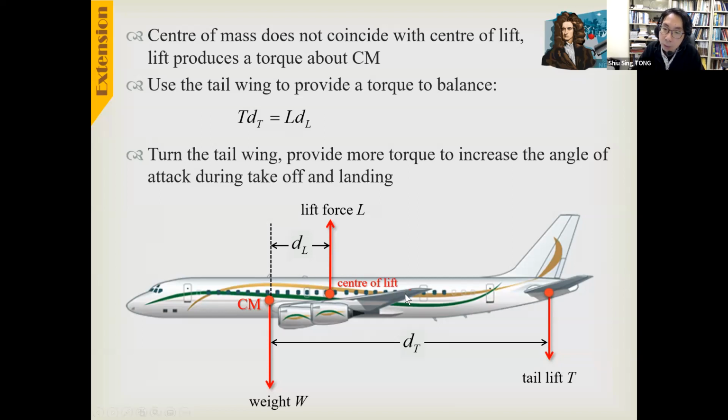So when it actually corrected the software, it corrected the lift force in the tail wing too much. Because when the airplane is gaining speed, the tail lift will be higher, so the plane will have its tip tilting upward, and the software tends to correct that.